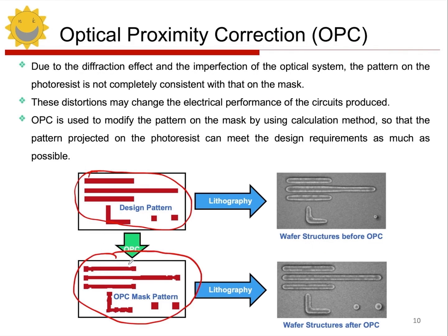These irregularities help compensate for the non-ideal characteristics of the lithography system, ensuring that the final processed pattern reflects our original design intent. Without OPC, the lithography process would not be able to accurately reproduce the intended design, leading to significant deviations. Otherwise, if we just use the original pattern without any adjustments, we could end up with significant losses in the final output, such as reduced yield or performance issues. That's why OPC is crucial. It ensures that the final product meets the high standards required in the industry, maintaining the integrity and functionality of the semiconductor devices.